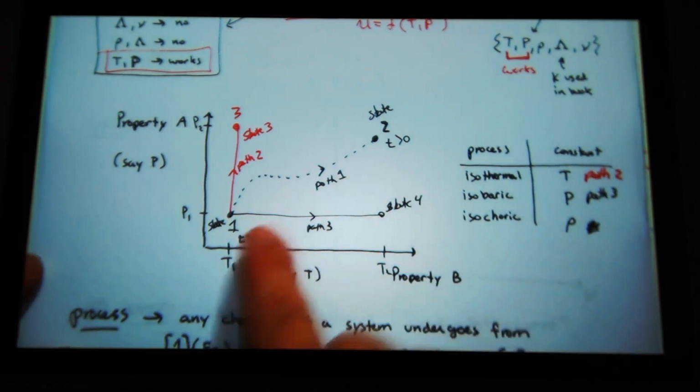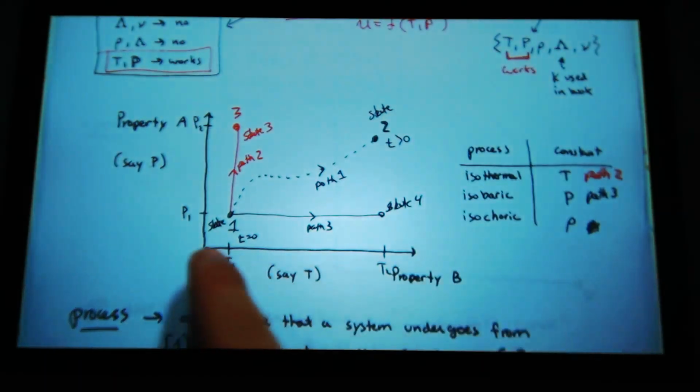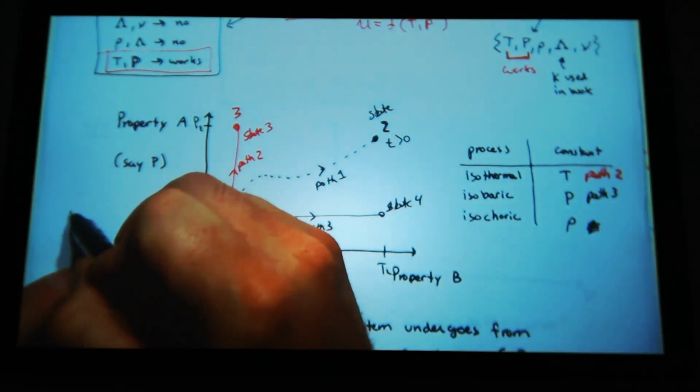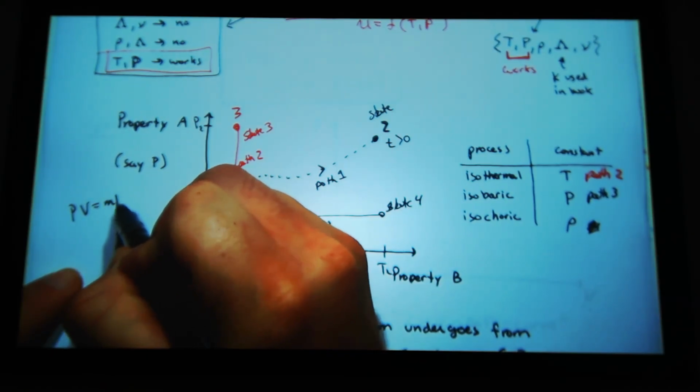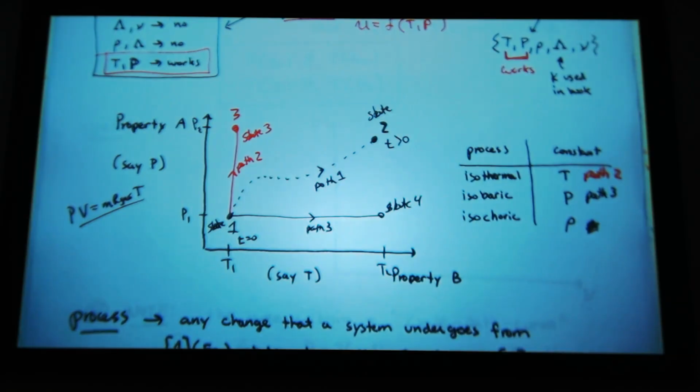And then for a constant volume process, given what the system was, if it's an ideal gas, I can draw that temperature and pressure relationship. So if it was a constant volume process, since you asked, and it's an ideal gas system, I have PV equals m R_gas T. So we say it's a constant volume process, there's no mass added.